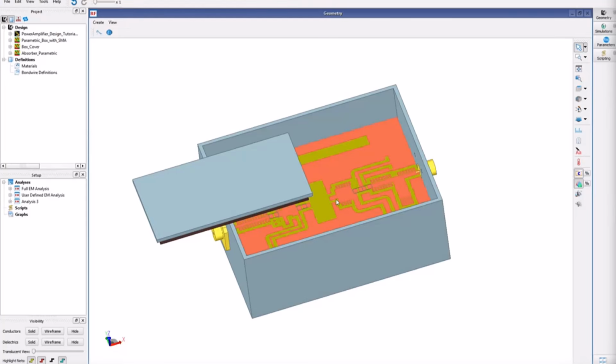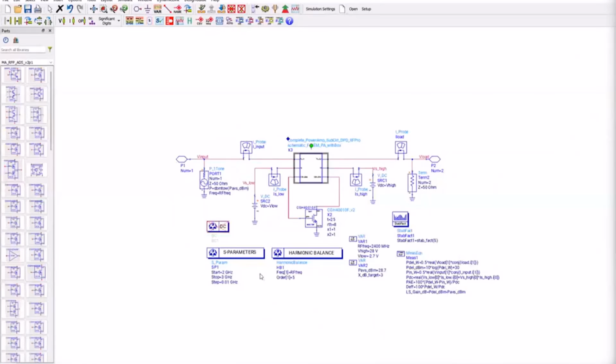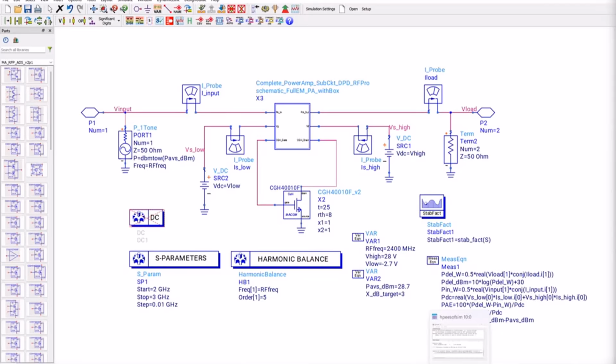And if something goes wrong, if your circuit is heavily inductor capacitor dependent, once you are in your circuit domain, you can set up optimization because your box is not changing, your SMA connector is not changing. Those things are as it is. You can even optimize your design to mitigate the effect of SMA connector, box, cavity, etc., which gets formed. So again, refer to the video I mentioned.